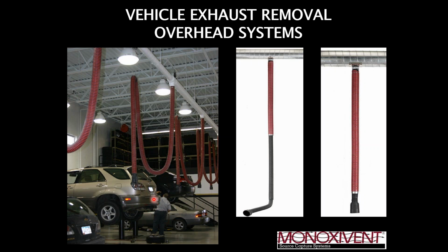And the reason we do that is twofold. Number one, and most importantly, if I'm bringing in ambient air, I'm certainly capturing everything that's coming through the tailpipe. Number two, that ambient air helps cool the exhaust as it goes through the equipment. And we'll talk about this in a few minutes, but when you're working on a high temp system, that ambient air helps cool that exhaust, and it can help save costs by reducing that temperature and allowing you to get a lower temp rated hose.